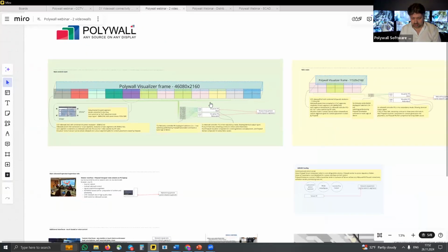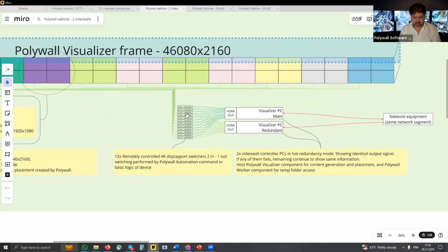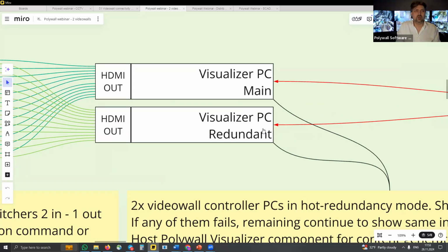And again, this kind of project is about how you can easily do it. Our partner was assembling the units by himself. So to drive the image for these video walls, again, we created daisy chain segments. So we minimized the number of outputs from 48 to just 12, just by using daisy chain segments.